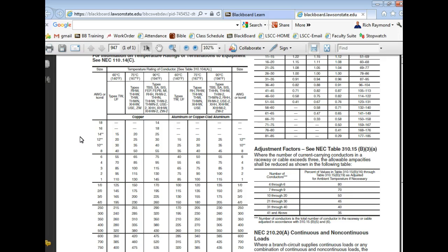The problem is we know that a lot of things affect the ampacity of a conductor. So we call this derating. How do you reduce it down depending on what environment it's going to run through, how many conductors you're going to pull together, which would be this table right here, right? You understand? This is the ampacity chart that the National Electrical Code uses.